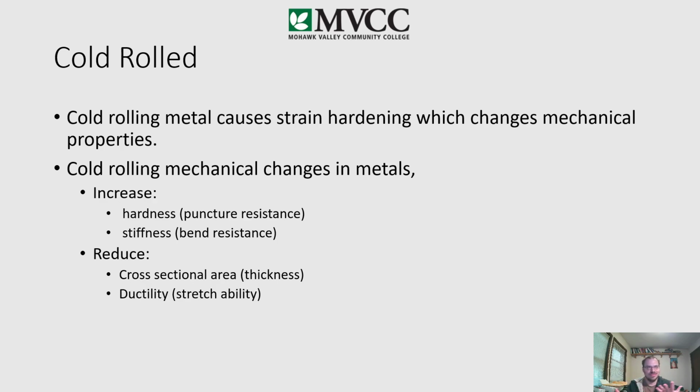So really, whether it's better or worse, what you're going to see from cold work is that as you do cold work, it's going to get harder, and it's going to get stiffer. The stiffness is going to increase. Bend resistance is going to go up. Puncture resistance is going to go up, but that ductility is going to go down. So it's not going to be able to stretch more.